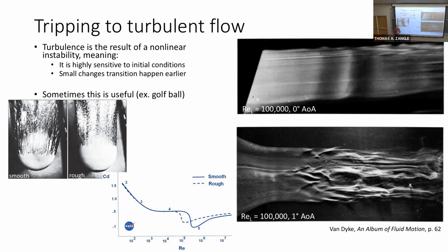Okay. And up till now, we've mainly been talking about laminar or turbulent, but now this transitional regime is really important, and that's because in this transitional regime, you can get wildly different kinds of behaviors, depending on exactly what your initial conditions were. And so you have to tread a little carefully around this transitional regime and know when to identify it. Okay. And so for external flow, we'll define the transitional regime as a Reynolds number of about 10 to the fifth to 10 to the sixth, so 100,000 to a million.